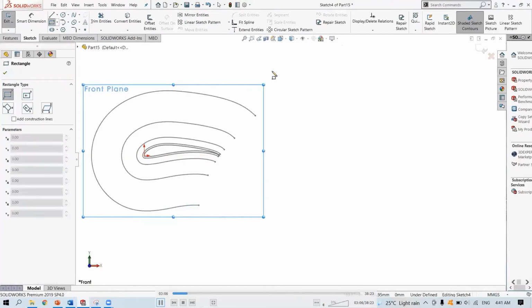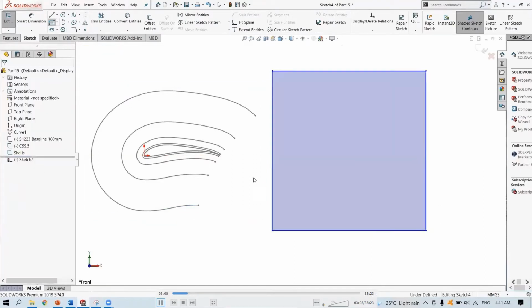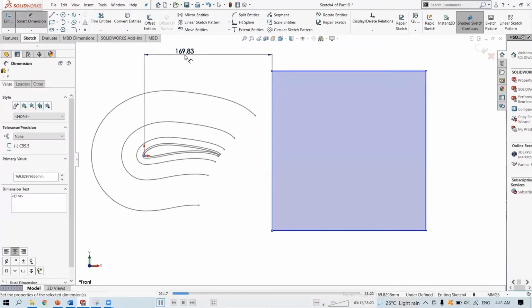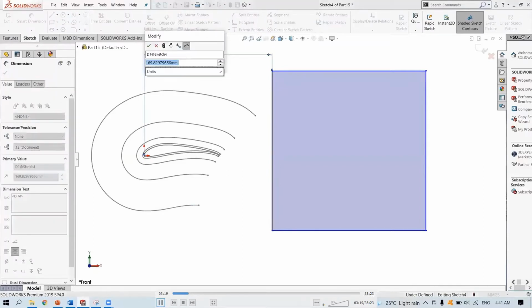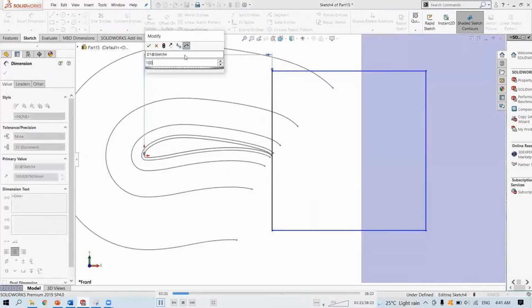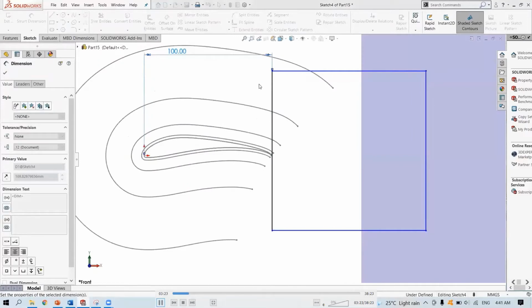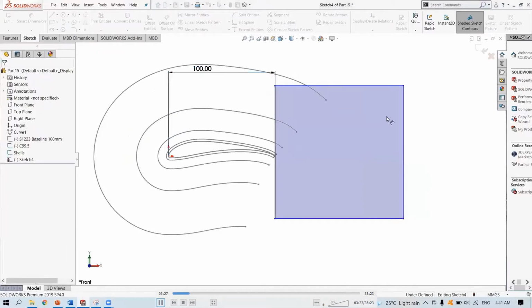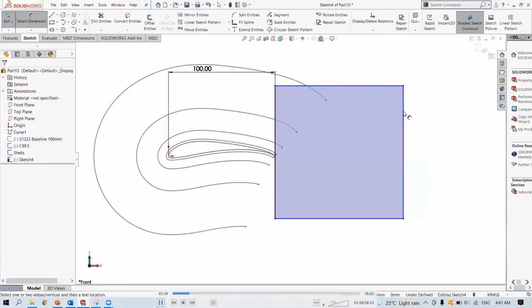Now let's introduce a region for the wake so that the mesh can be relaxed. So we'll start from the trailing edge. So this is 100. And I'm going to set the length for the mesh to relax, just another chord length.